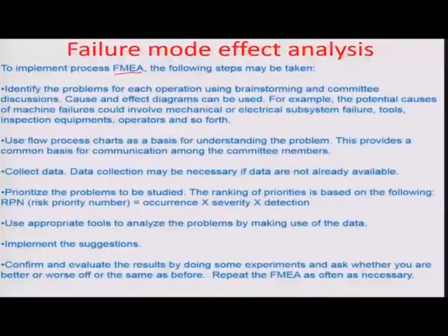So what we are going to do is, through an FMEA process, try to see if we can make a system level and a process level improvement so that this defect or failure mode comes down. The failure in this particular case would be related to rusting of the door. So the following steps are usually followed in the algorithm for doing FMEA.